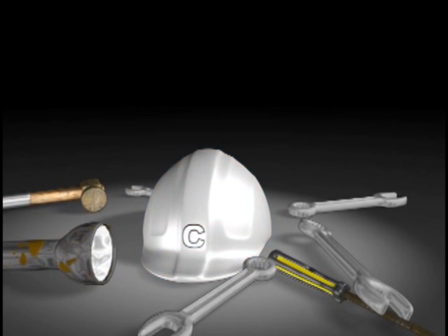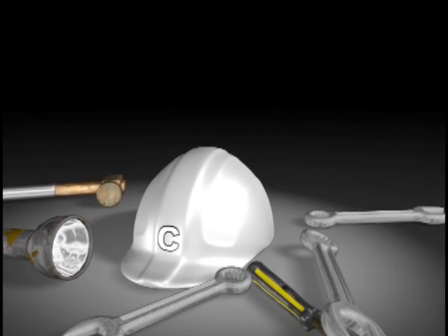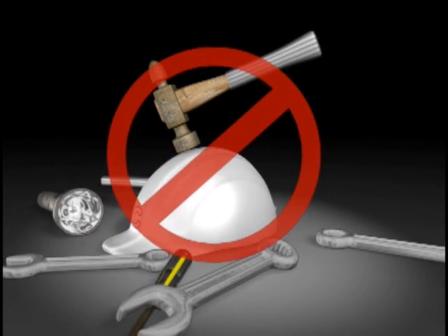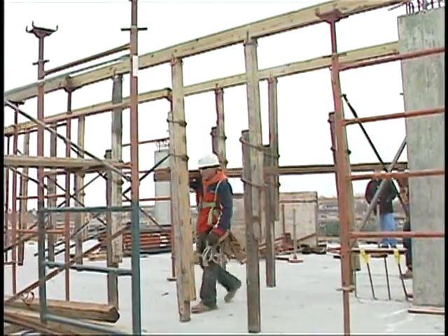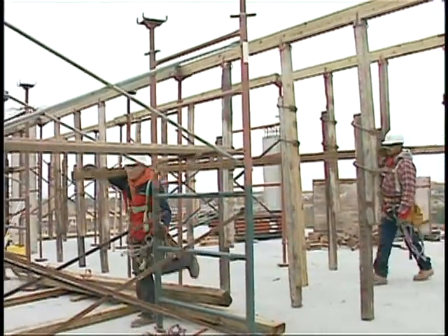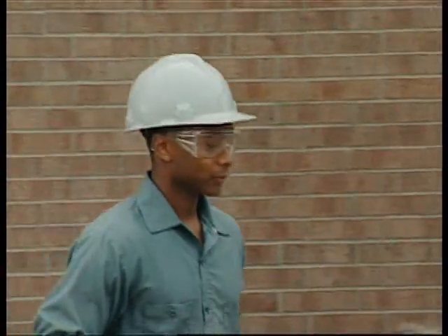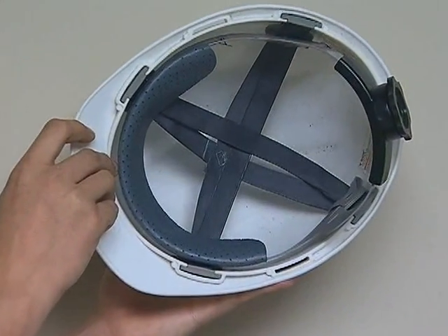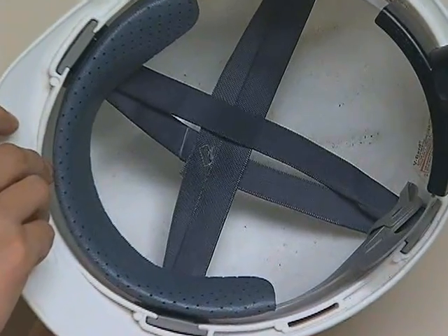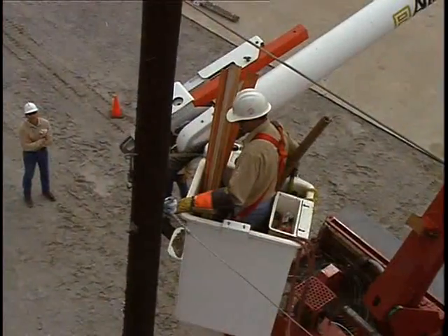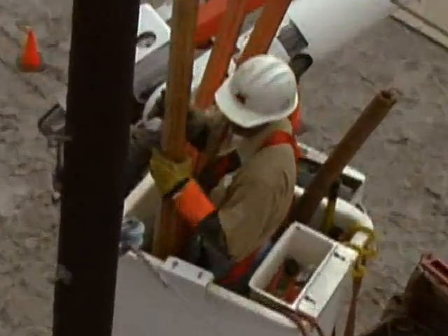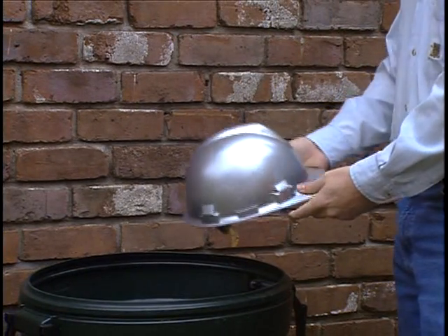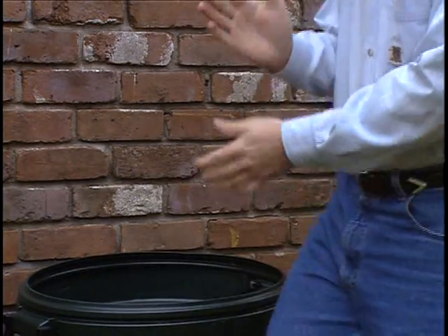Class C hard hats are designed for comfort and limited protection against bumps, but not falling objects. These are sometimes referred to as bump hats. Hard hats provide features that protect the head from impact by providing a hard shell that resists and deflects objects from hitting the head. The suspension system inside the hat acts as a shock absorber against falling objects. Some hard hats insulate against electrical shock. A metal hard hat is outlawed at most construction sites and facilities since it offers no electrical protection.